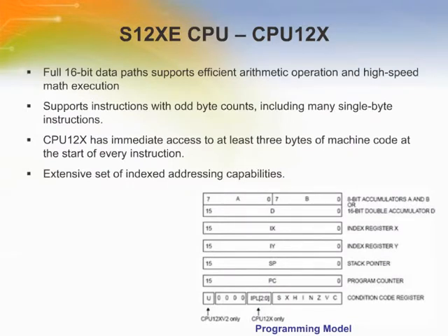The CPU-12X is a high-speed 16-bit processing CPU. The CPU-12X instruction set is a proper superset of the M68HC11 instruction set. The CPU-12X retains all of the instruction sets of the original CPU-12. The only exception that requires consideration is that the interrupt stack frame on the CPU-12X is increased by 1 byte due to the extended condition control register. Dedicated address generation logic and pipelined execution improves the CPU-12X performance relative to the CPU-12 architecture.